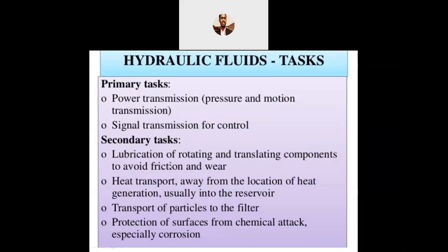If you use water, can it do this lubrication? It is not possible. That is a major one. Okay, now let me come back. The secondary task of this hydraulic fluid, I'm talking about only the fluid, my dear friends, is to lubricate the rotating or translating components to avoid friction and wear.